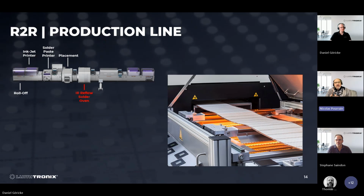After the pick and place, you have the LED, so you need to go into a reflow oven. In that case, in our production line, we have an infrared heating element. There is temperature measurement by zone, and you can control each heating element separately. It's very efficient and very compact compared to a traditional multi-zone reflow oven.